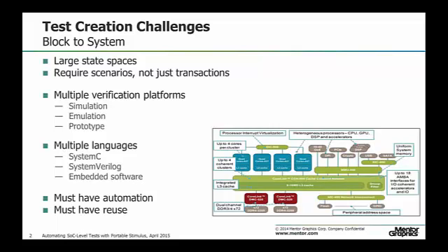Typically we also see many different languages, not just a single language. Maybe you start with SystemC for virtual prototyping or performance analysis, and then later on during the implementation phase, SystemVerilog is used, or software-driven verification using real embedded software running on processor cores. So to manage all this complexity, you must have a lot of automation to remove manual translations, manual steps, and you must have a high degree of reuse, both vertically and horizontally, as we have seen during the previous presentations.